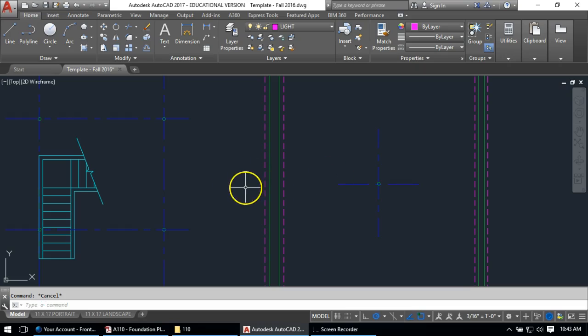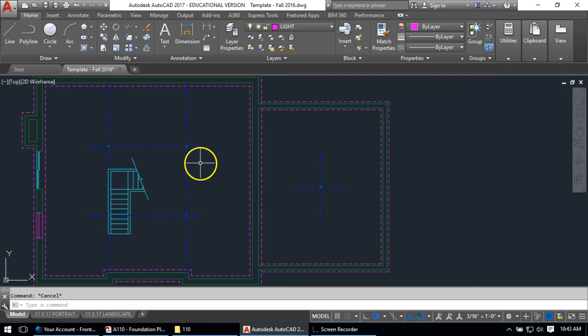Now you notice there's these dotted lines around there. That's the foundation for the columns. There's no dimension on this, but if we go over to page 3 of our instructions, I think they might be over here. Yes, it says 3 foot by 3 foot by 12 foot footing in 4 locations, so that must be these guys. And then the next one says 4 by 4 foot, so that must be these guys here.